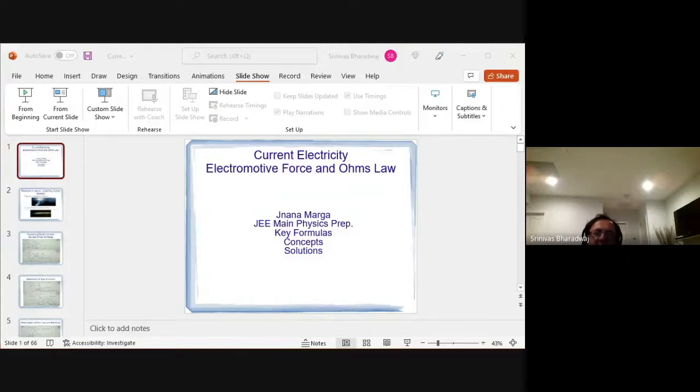Alpha is the temperature coefficient of resistance, the coefficient of resistance with temperature. So 1 plus alpha times delta T. As the temperature goes up, the resistance increases, and they say it's a linear increase. Typically, the second degree term is dropped for small changes in temperature; for larger changes they will introduce it.